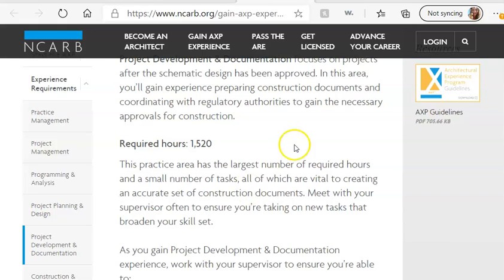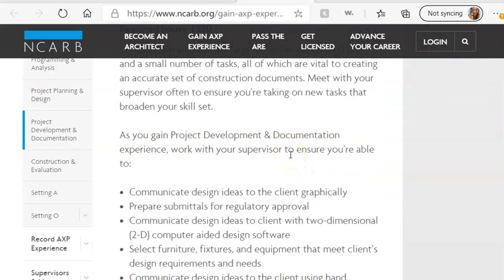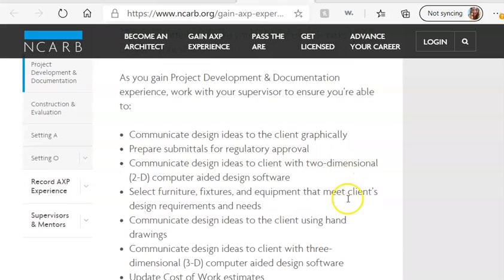And this is where you actually detail, okay, this is where the flashing needs to go in relation to the insulation and the window assembly. These are how all the components go together. This is where you select the actual materials, the integral details of how a design goes together. This is when you talk to the client and understand what the actual final building design is. This is when you provide them the documents that they will take to bid.